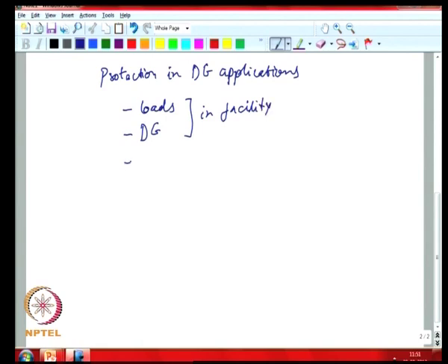But you also saw that you could operate your DG and potentially damage your neighbor's equipment, because of things like out of phase reclosing. And you want to protect the distribution system itself, because in a situation of unintentional islanding we saw that the operation of the DG can potentially damage your actual distribution feeder itself.